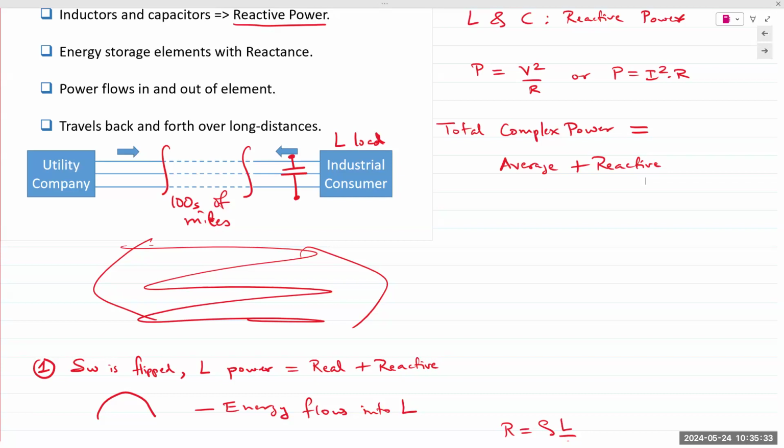For all other combinations, of the 10 units of energy, one unit might go to the inductor, another might go to the capacitor, so your resistor might get 8 or less than 10. But at that one particular frequency, the resonant frequency, the inductor and capacitor are perfectly balanced. The energy requirements drop to 0. Everything is sent from the source to the resistor. And that is a perfect example of a perfectly balanced power factor corrected system.